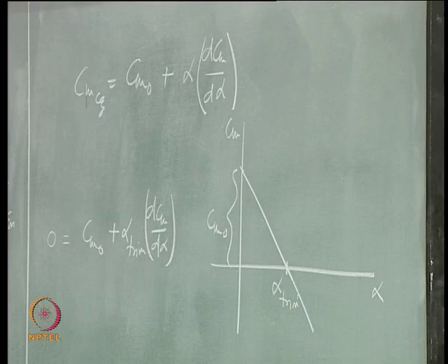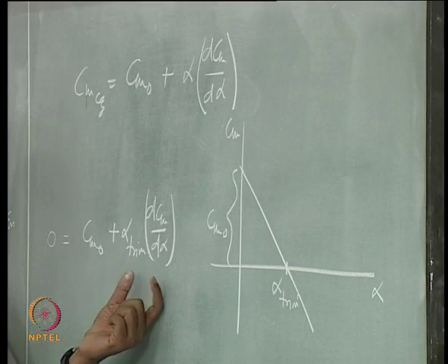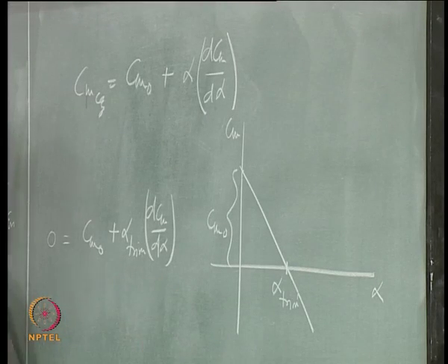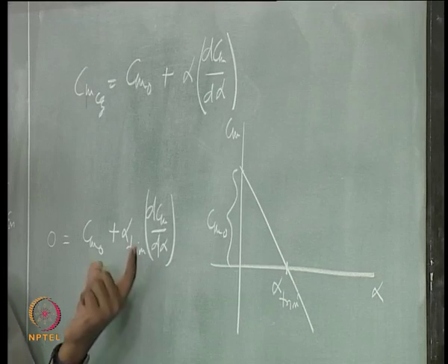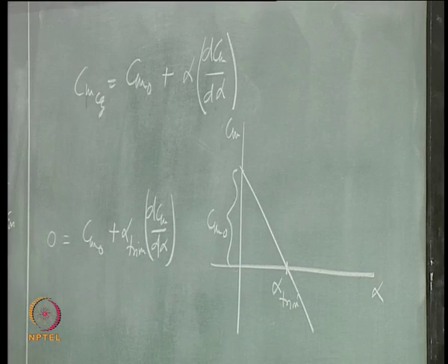One is, of course, we started with, right. In the last class we said that we are going to use a flap at the trailing edge of the horizontal tail, which is called elevator, but let us say now we will go into that a little later. Change the camber of the wing airfoil itself, right.